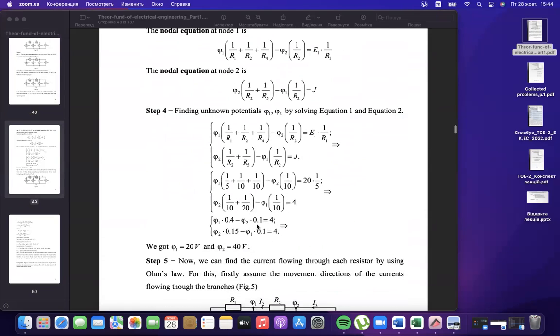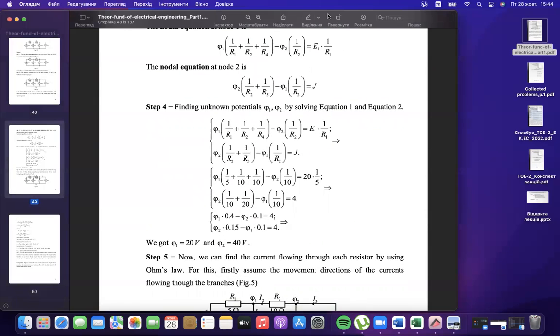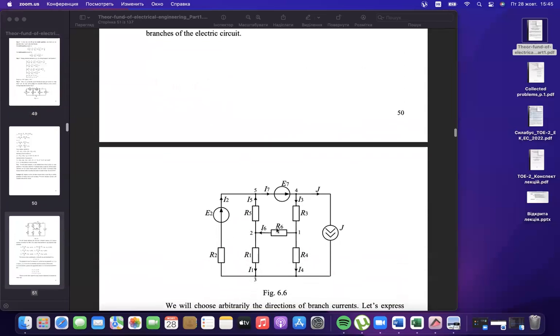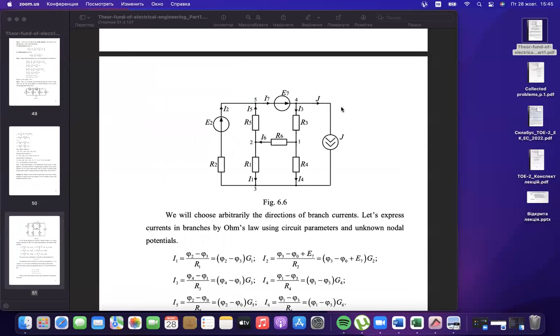If you have an ideal conductor, then in each equation you have an infinitely high value and you cannot solve it, because the value is infinitely high. How to deal with this case? For this case, you should write the equation in such a form that this infinity will not be taken into account inside the equation. How should it be done? By choosing the ground, the 0 potential.